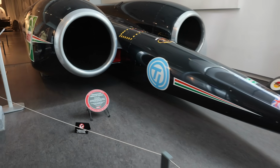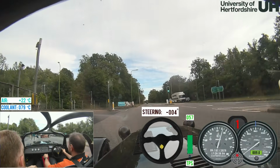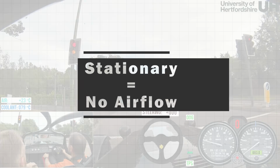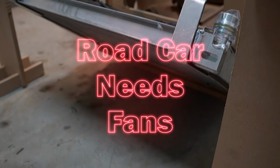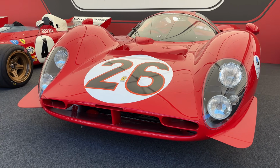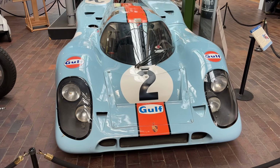Now, one of the big implications that we have with this, with the road car with lower speeds and often sitting at the lights at a minimum of 0 kilometers an hour, is there's going to be a lot less airflow to the radiator for a given opening and radiator size. That means a road car is going to need fans for when the car is stationary in order to keep the car cool. And because a race car is going to have a lot more airflow, you can potentially get away with a much smaller opening size. In fact, you need to tune that to ensure that you're not running too much drag in your race car.